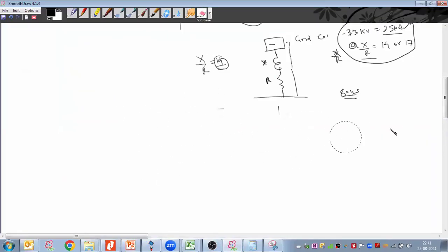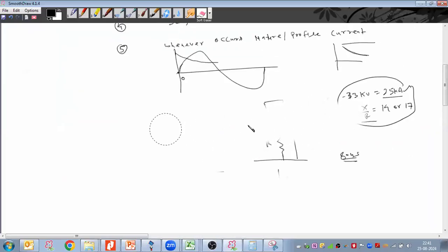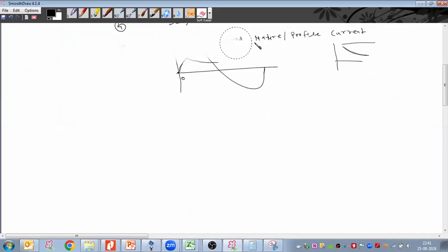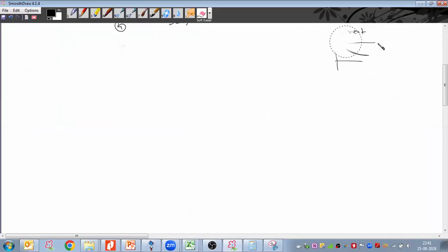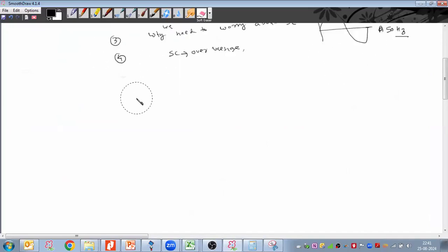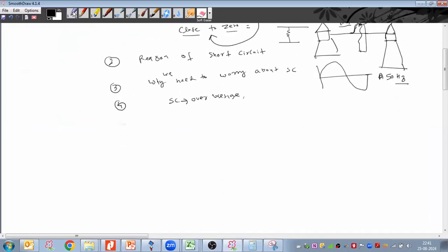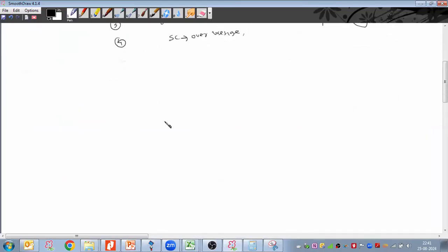What we discussed is the basic concept: what is short circuit, why short circuit, the nature of short circuit. The short circuit rating we select is the symmetrical short circuit rating, like 25, 40 kiloampere, 31.5 kiloampere. Now, how will you select it, what would be your approach for the short circuit current rating? So we should know what type of project we are working on.